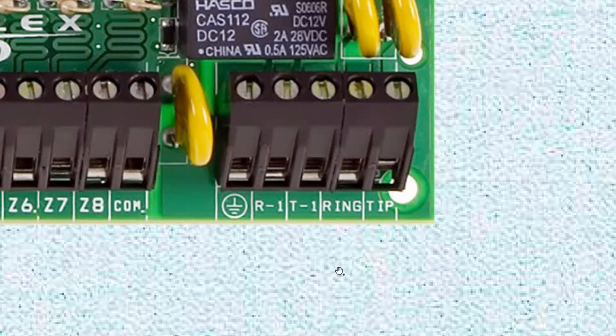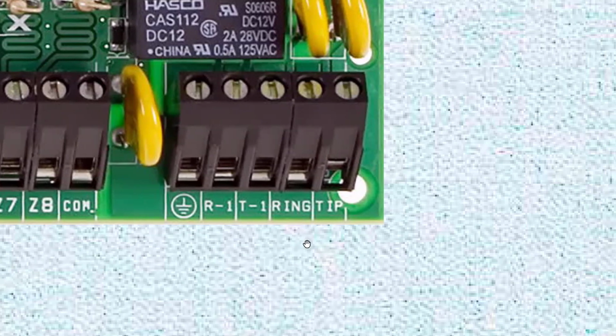How does that work if it's working on POTS? Well, the telephone signal is being brought in from outside, and then it's being redistributed to the rest of the house. You interrupt that connection, and before the telephone line gets out to the rest of the house, straight from the city, straight from outside, you connect this telephone line to the tip and ring here.